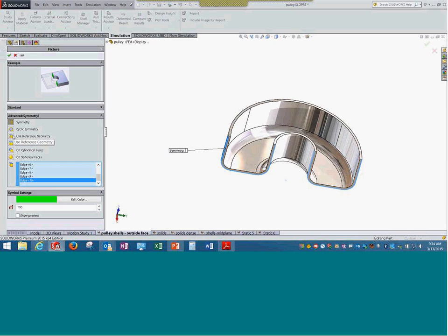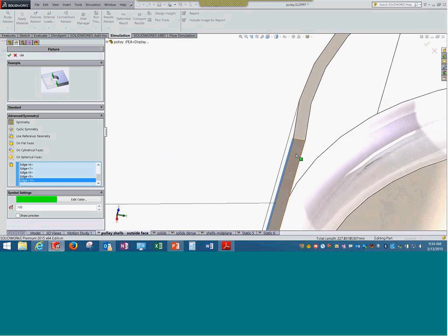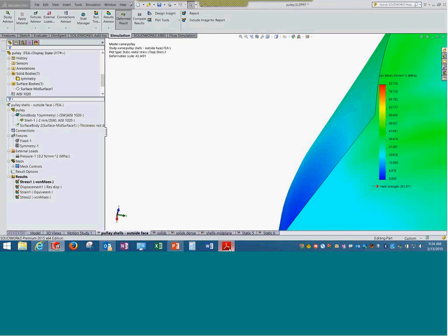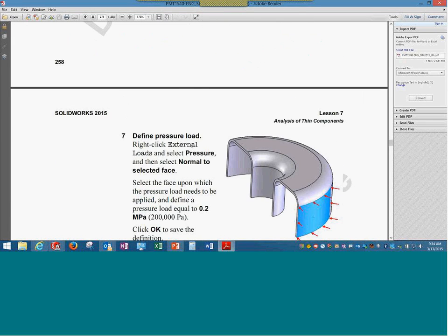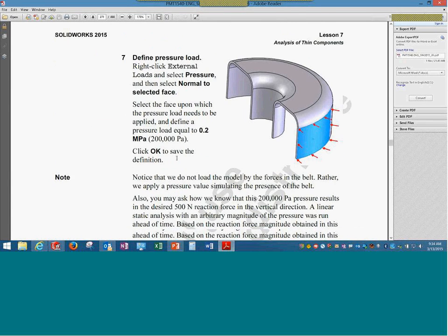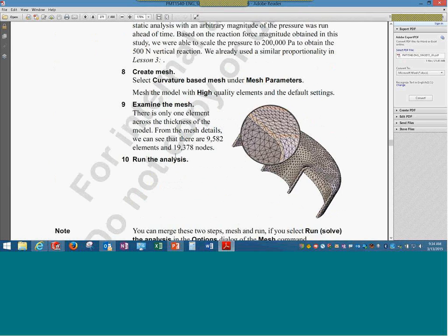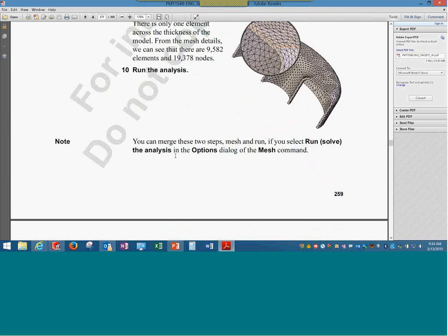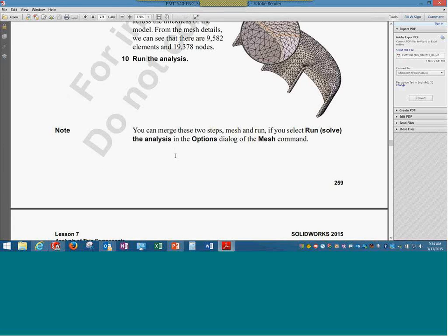If I put it simply, we need to just restrain the degree of freedom particular to the surface where it is being held. You can use the reference geometry option and hold it. That's it. Earlier we did not have this option. We had to imagine all the things and do it. We did not even have the option of visualizing the location of the shell element, and that made a big difference.